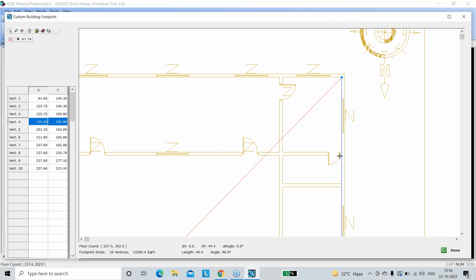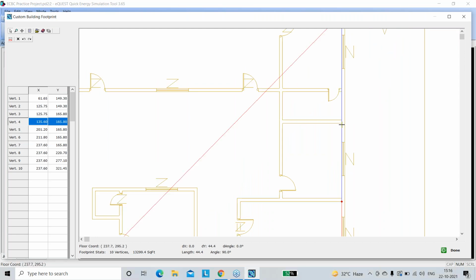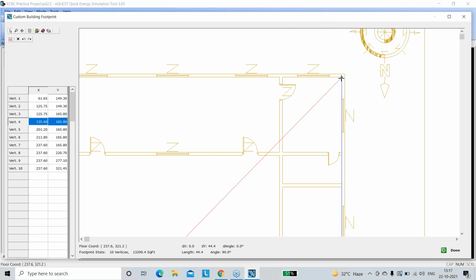And if you put a point here, put a point here, and this does not exactly superimpose on this, then it will give an error or at least a warning. So hence, it is important that we create the geometry, and then we keep on dragging them to every floor plan point.